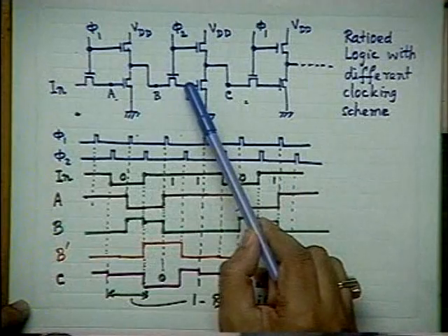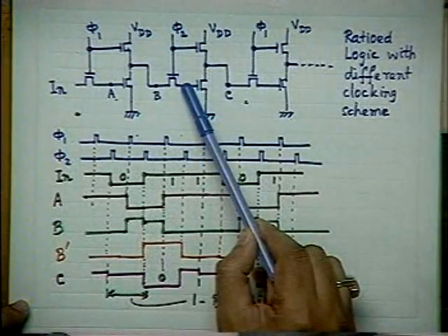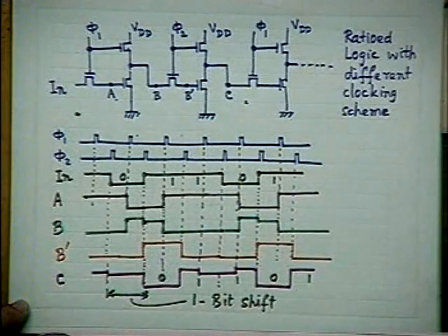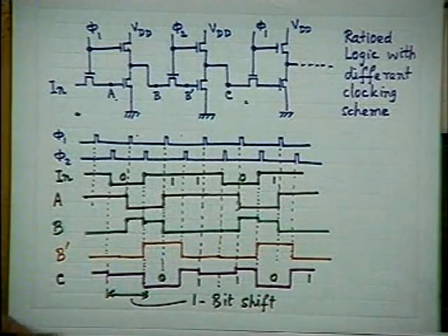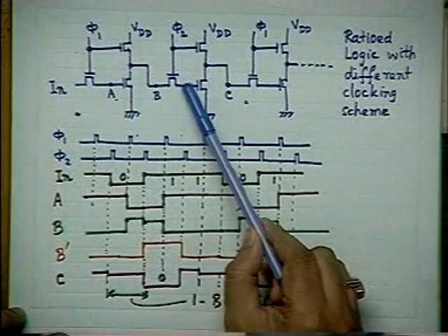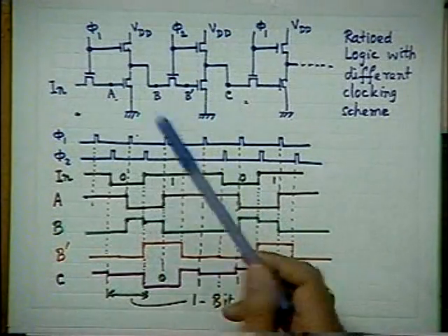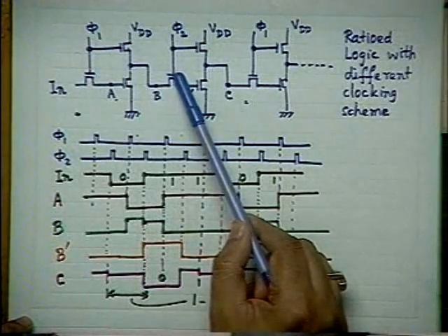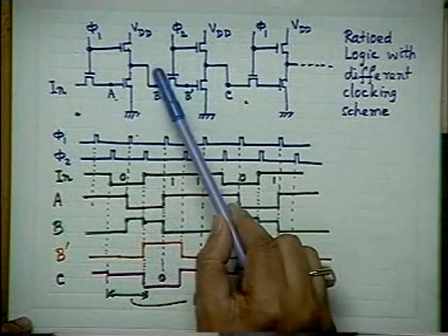And I also have a capacitance between the drain and substrate of this transistor, which is usually reverse biased, maybe 0 bias to reverse bias, in a certain range. If this voltage is high, then it is reverse biased, but if this voltage is low, then it is not biased. But there is a junction capacitance between the drain and the substrate of this MOSFET.